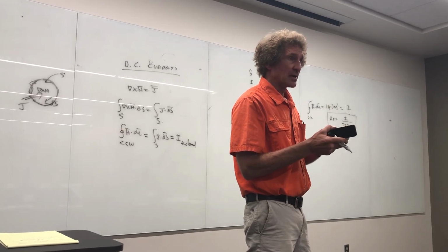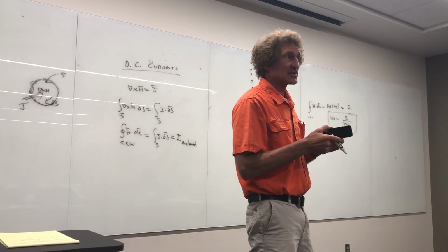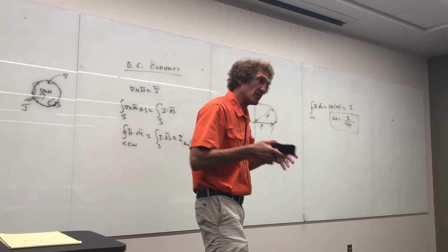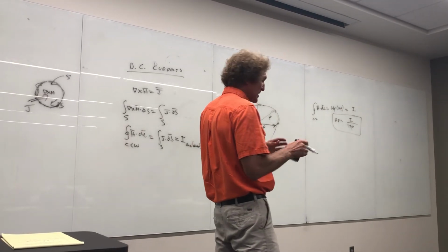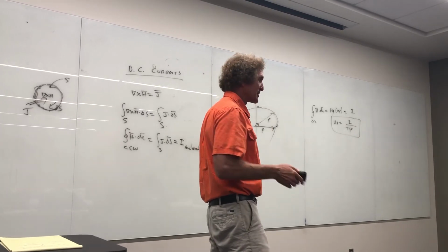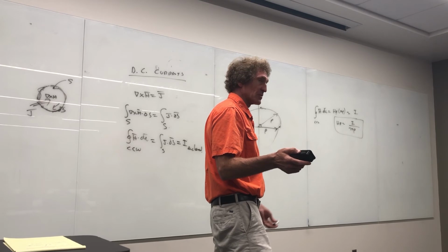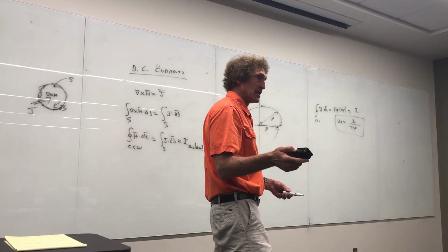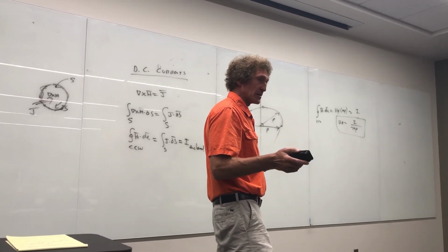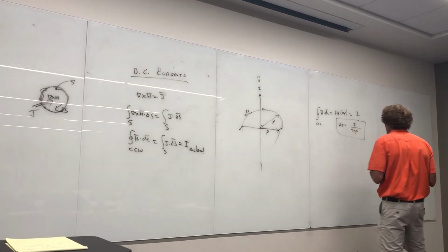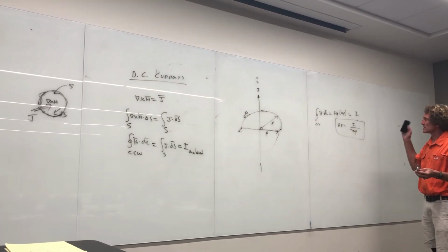If you want a kajillion watts, that's the kind of thing, because the watts only last for an instant, but you can get all the power out. There are other tricks too, and I'm not an advocate of spherical capacitors, because frankly, the lead inductance for the most part is what limits discharges these days. It's not the internal inductance, but keep that in mind. If you ever need a really fast discharge capacitor, use a spherical capacitor.